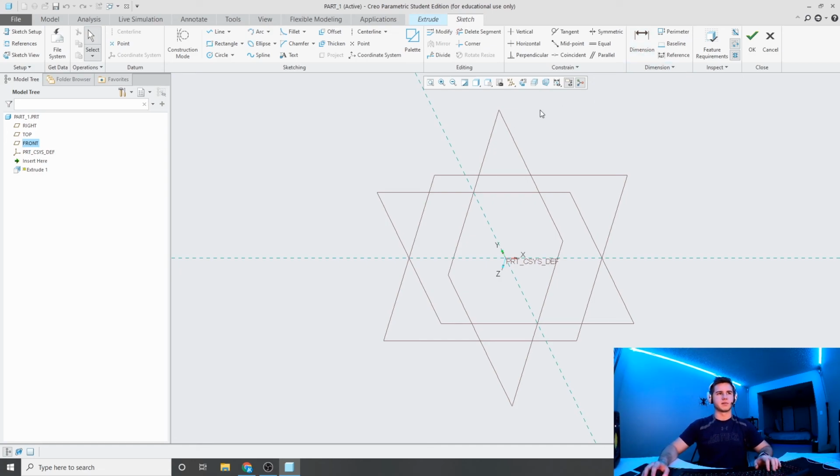So for this quick example, I'm just going to go through the example I just talked about, where I sketched something in 2D and then extruded it to make a 3D object. For this, I'm just going to make a simple cube with a hole in it. So I'm going to go over here, and a cube, in 2D, is a square or rectangle. So I'm going to go here, make a center rectangle.